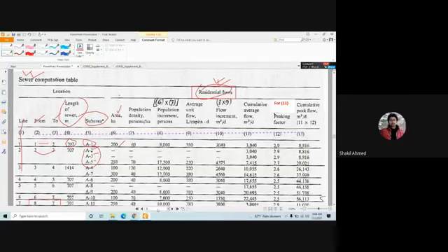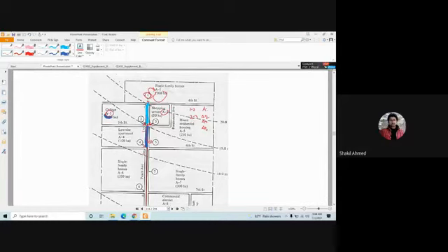And A2, A3 is what? College. Is it residential? No, sir. Shopping center. Is it residential? No, sir. So A2, A3 will not contribute here. Yes, they will contribute in this pipe, that's true, but we will not include this in the table. We'll include this in the table of commercial and institutional. Clear? Of course, they are contributing in this pipe, but we will not write this in this table. We will write this in the respective table.